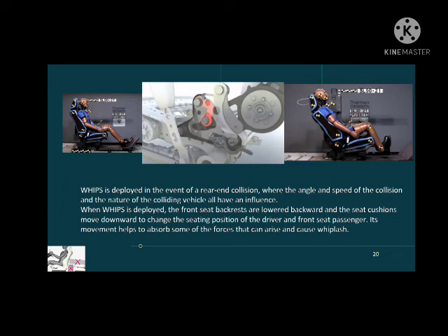The acceleration level is kept low by letting the backrest move rearwards in a controlled way. This is accomplished by the primary phase being a rearward motion of the seat backrest. The character of this motion is essentially translational, for example without rotation.